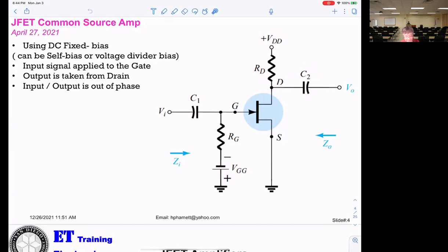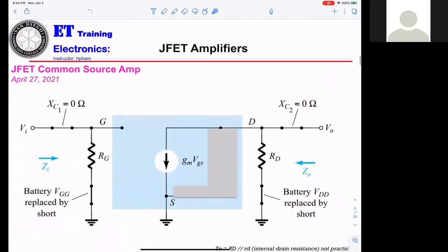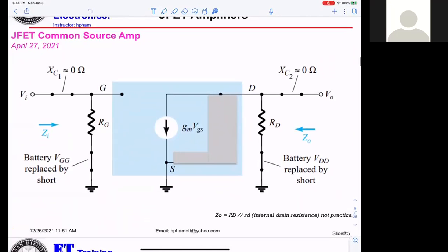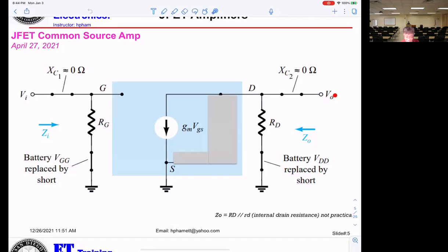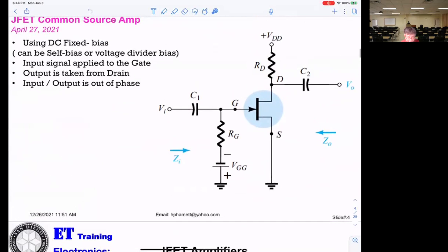C2 will be shorted. So, Mr. Pham, you're saying if you had a resistance on the other side of that, since the capacitor was shorted, then it's in parallel, if it was another resistor there. You don't have any load resistance for this circuit. But if there was one, they would be in parallel. Exactly. If you get a loading, right now this circuitry has no loading.